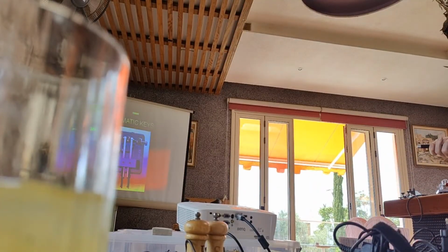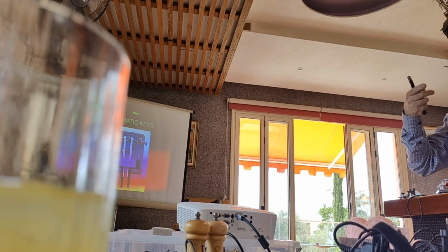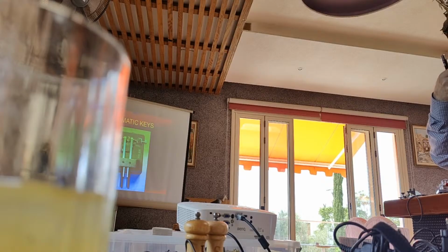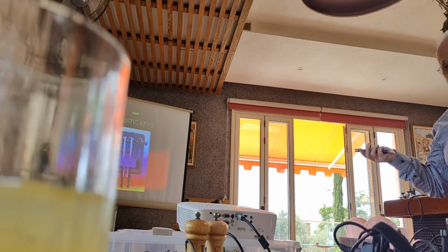This brass knob has embedded in it a ring magnet, which is magnetized on the face. And there's a matching ring magnet there. So if you have the two north poles facing each other, they repel. So by screwing this in, you increase the repulsive force, which increases the tension without any springs. How about that?